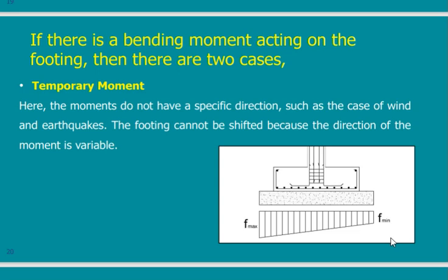Here, in this direction, because I'm acting with a moment, I increase the moment, every time a little bit. When my stress due to moment is equal to the stress due to normal force, then I'm at the brink. I will start to lift the footing. In this case, this value will be 0. At this time exactly, it will be 0.